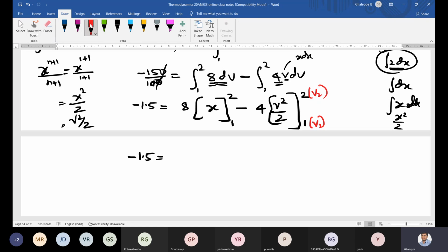Okay, here look at this value dV. This is change in volume. Here it is change in volume, so we have to write the limits in terms of volume. If the given condition were like this, 8 dP, then you have to take P1 to P2, because change in pressure you need. So here V1 and here V2. So here X is not there, it is V. Okay, next.